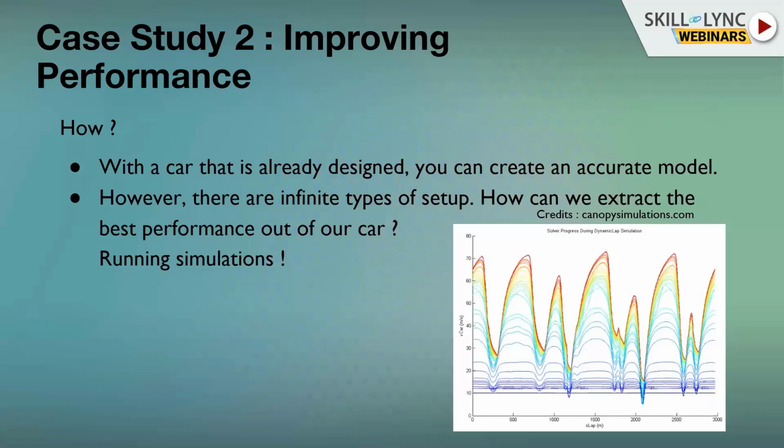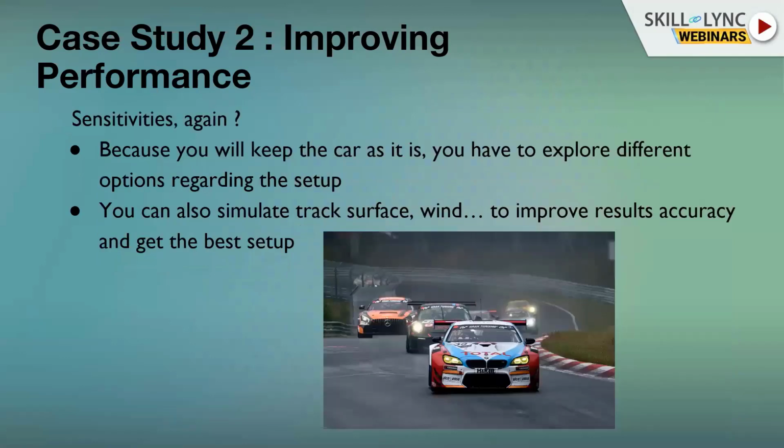And that's why Laptime simulation is also time consuming. As I told you earlier, it's a time saver, but it can also be time consuming, depending on how you will code your Laptime simulation. So going back to our Formula 2 example, when you have an infinite number of setups, what you can do is run a huge amount of simulations and decide what's the best setup for your car.